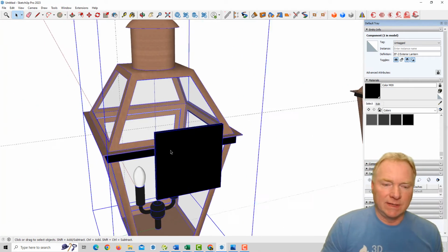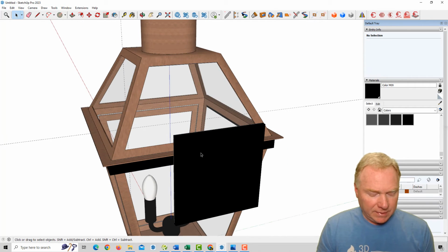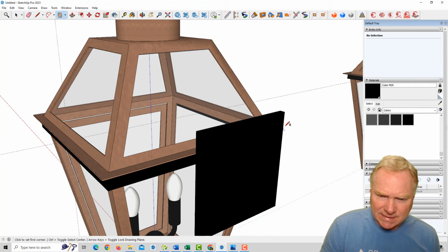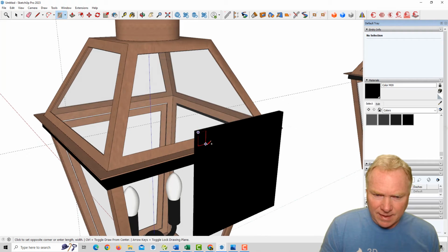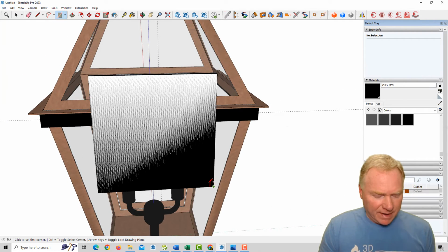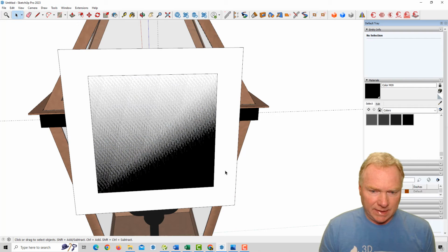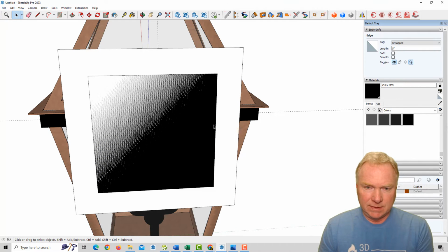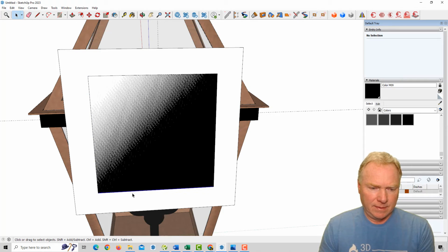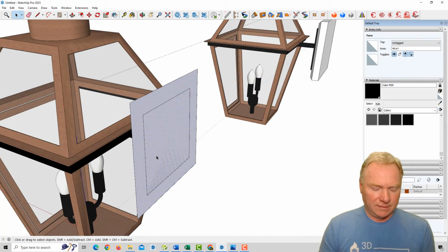The last thing I need to do is get this block on here. We have a mounting block. I'm going to draw a rectangle on the back side of this, and it's right now 5 by 5. If I use F and go out 1 inch, that'll give me 7 inches, and I can delete these edges that were left. Now I've got this face that's 7 by 7.